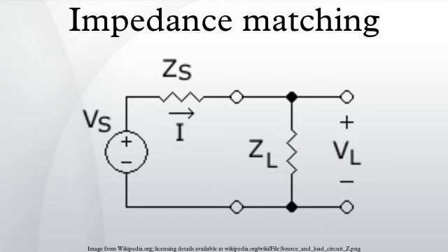In general, it is not theoretically possible to achieve perfect impedance matching at all frequencies with a network of discrete components. Impedance matching networks are designed with a definite bandwidth, take the form of a filter, and use filter theory in their design. Applications requiring only a narrow bandwidth, such as radio tuners and transmitters, might use a simple tuned filter such as a stub. This would provide a perfect match at one specific frequency only. Wide bandwidth matching requires filters with multiple sections.